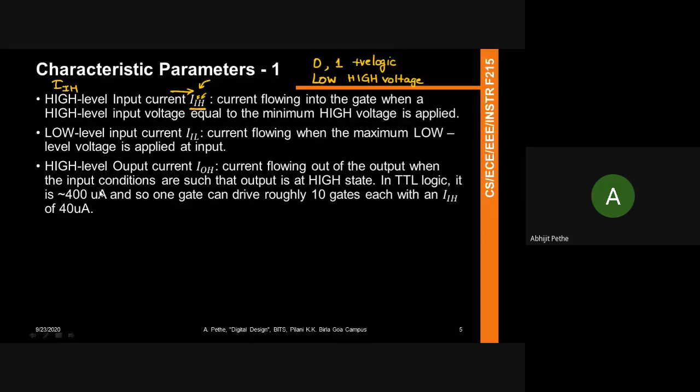So when I've given a ratio of 1 to 10, that is, I've taken the output of one gate and fed it into 10 inputs, I can say that the fan out of this technology is 10, because I can take the output of one gate and feed it roughly into 10 gates without losing the value of high, right?